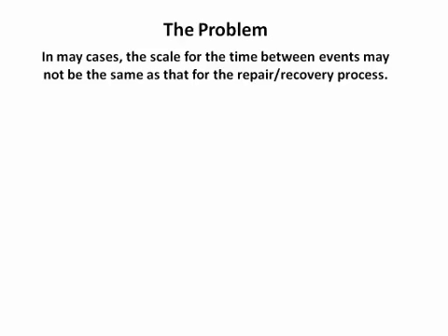What I mean by that is if you connect to a TD connector, the TD connector advances when an item leaves an activity block. So using that signal, your failures will always occur just as items leave the affected activity. If you, for instance, put an info block in front of the activity and count items as they enter, your failures will always occur right when the activity starts processing. Those are both valid models for different situations. There's nothing inherently wrong with either one of them.